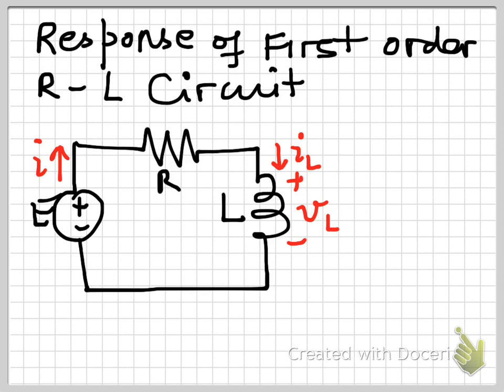We're looking at the response of a first order RL circuit. So you have R and L connected in series to a voltage source E. Here we're looking for the response of IL as a function of t. You're expected to use all the basic laws, including Ohm's law, KVL, and KCL, at all possible loops and nodes, or for the components as well, and use the solution to the differential equation. Here I'm just writing the final solution.